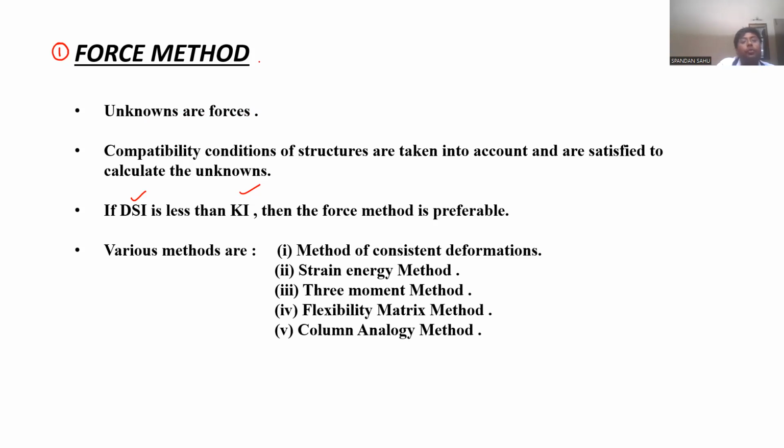So the force method. I am just highlighting all the important points because you must have gone through the week 8 lectures, where sir has discussed in detail. I am not going into detail, otherwise we won't be able to solve some problems, which is the main motto of this class. In this force method, as the name suggests, forces will be the unknowns. Second, in this method, compatibility conditions of the structure are taken into account and satisfied to calculate the unknowns, that is the forces. We will see how those compatibility conditions are written to solve statically indeterminate problems.